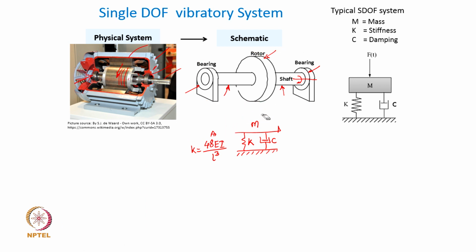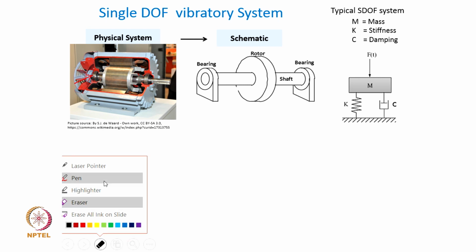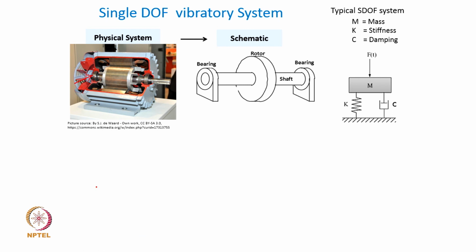Now, this is all with our understanding and our knowledge of this particular system, that we are saying that the shaft is treated as the most flexible element in this particular case. But you may as well see, and someone may question, that the shaft appears to be reasonably small in length, and have we checked whether really the bearings here are that rigid, that we should treat the bearings to be rigid enough and the shaft flexible enough.